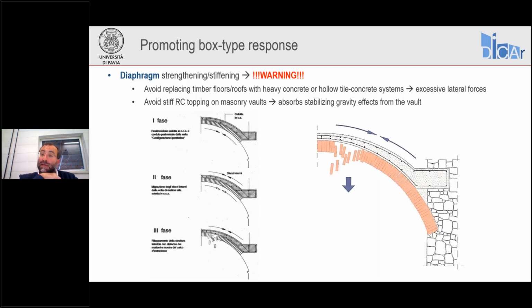And if we now shake the masonry vault, we may lose the bricks, except for those around shear connectors, because these bricks are not sufficiently compressed against each other anymore. Now, the forces, the compressive action, has moved towards the new concrete vault. It has basically left the existing vault unloaded. And this is completely undesirable. It can result, and it has resulted in the past, in collapse of the vaults. So it is something that also should be extremely avoided.